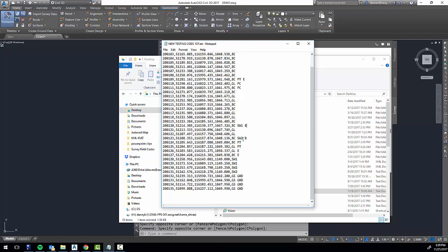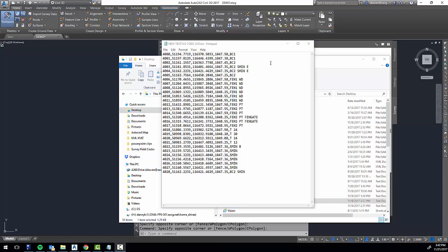So basically, what I'm getting at here is we got 1 point, and it's got 2 identifiers, and 2 feature lines are being run off of that. So I've got a sidewalk line work coming off of the same point. It's got the one point number, but I got 2 figures pulling off that, or 2 lines. So back of curb and sidewalk. So that eliminates the need for the recalling of points. So therefore, you're not drawing up the sidewalk, trying to notate that in your field book. Very powerful.